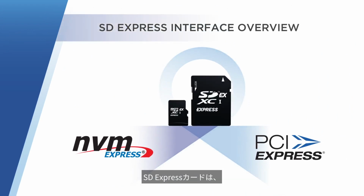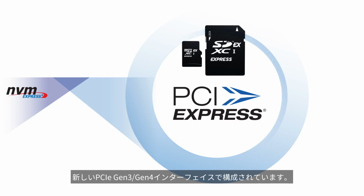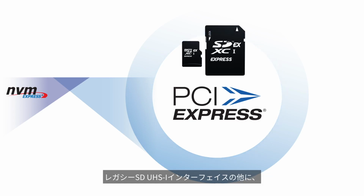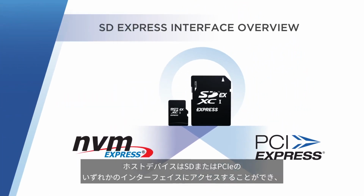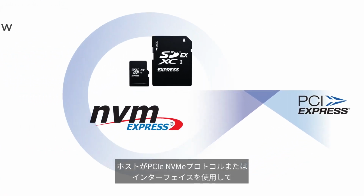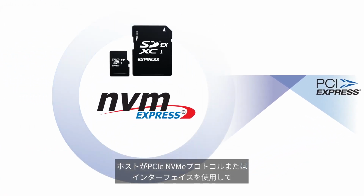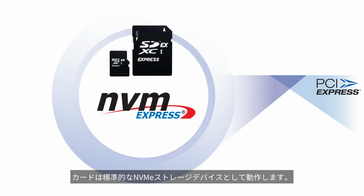An SD Express card consists of a new PCIe interface using either single or dual channels based on Gen 3 or Gen 4, beside the legacy SD UHS-1 interface. The host device may access either of the interfaces, SD or PCIe, and the card automatically detects the protocol and will operate accordingly. If the host accesses the SD Express card by using the PCIe NVMe protocol or interface, the card behaves as a standard NVMe storage device.